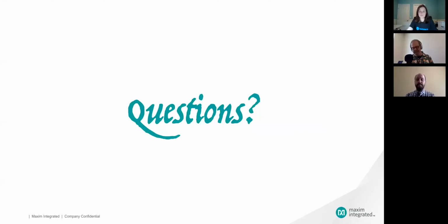Yeah, and one more thing, the RTC is a critical piece of this, because the RTC lives in our always-on domain. So the power domain is always going to be available. That means you can shut down the processor, run it in like low power mode 0 or low power mode 1. The core itself is now turned off. You're drawing literally microwatts of power at this point, but the RTC can wake you and then get you going again. Those wake-from-sleep examples are already there in the Eclipse package that you get, and I encourage you to have a look at those.